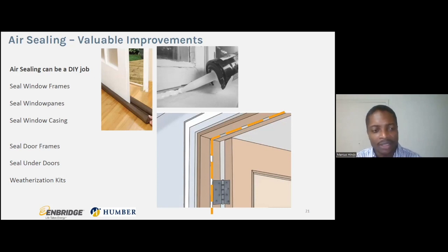Now the doors, another thing that we'll talk about in coming slides. I'll just go through the windows first and then we'll get to the doors. But the main thing that you want to do with your doors as well is make sure that the frame is well sealed. You want to make sure that under the door itself is well sealed as well. And you can actually use a weatherization kit for that.